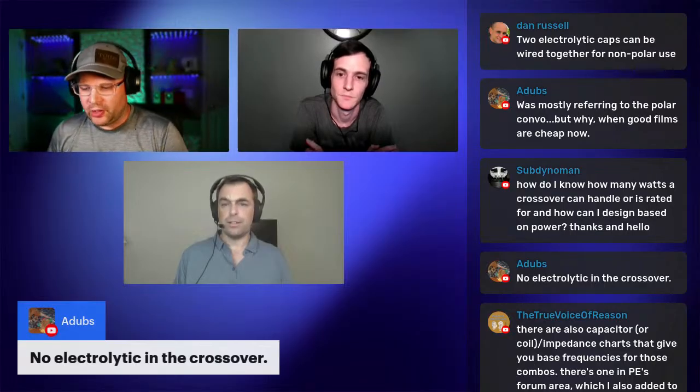Yeah, like if you need 100 microfarads or something, it can get expensive, so you want to go electrolytic. One other thing is electrolytics, for the equivalent value, often have a higher resistance. A typical capacitor may be really low, where an electrolytic could be 5 or 10 times more than what you're expecting. So if you're replacing parts haphazardly or upgrading your crossover components and you don't have any way to simulate that, use the same type of components. Don't swap a film capacitor in where an electrolytic was, or at least know there are consequences for doing that.